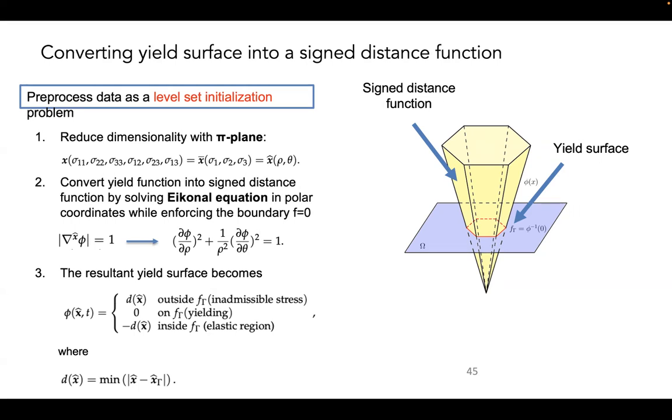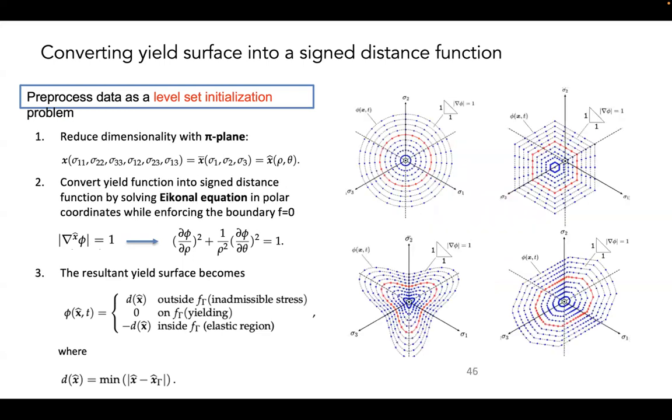And this is related to the magnitude of the plastic flow, which you would get from solving the system of equations. So if you pick different signs or different values, you would get a different plastic multiplier. In the literature, sometimes they have a yield surface that is not a signed distance function, or has some funny magnitude, and then they just normalize it in the implementation. So you kind of get the same thing. In general, I just want to show that you can get any different shape.